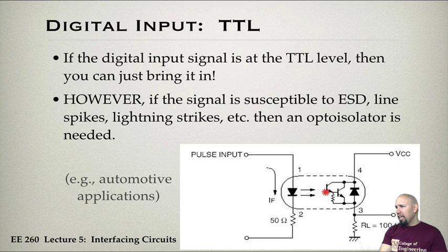So the LED is connected to what's called a photo receiver. Okay, and so that will pick up voltage, and the output voltage then will basically be the same as the pulse. But if this goes too large, it'll still turn on the LED, but this side of the circuit, which is where your Arduino is connected, is not physically connected. It's connected optically. So the light here is what communicates this pulse or this digital signal to this output.